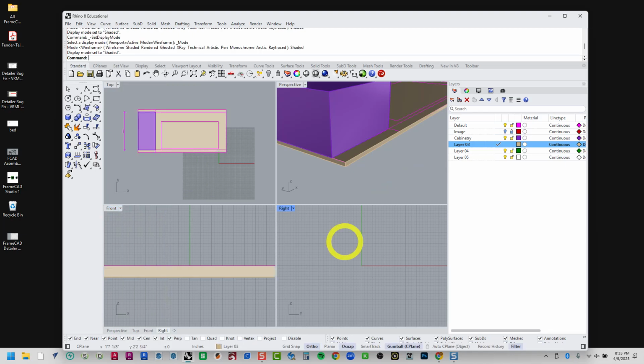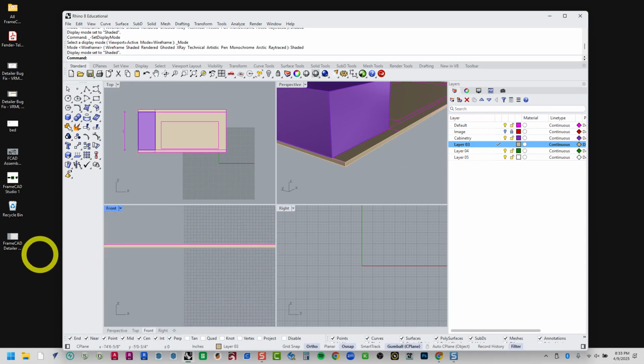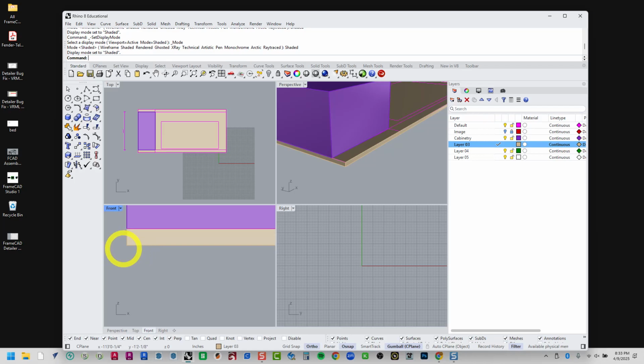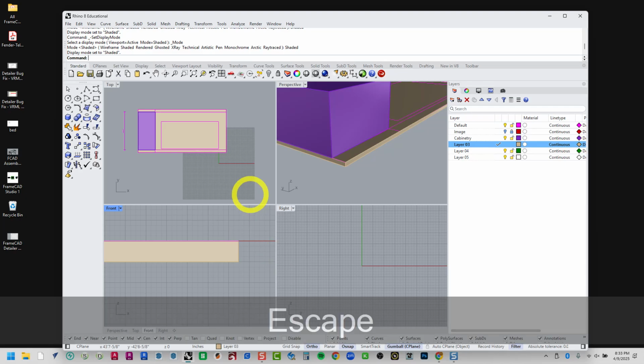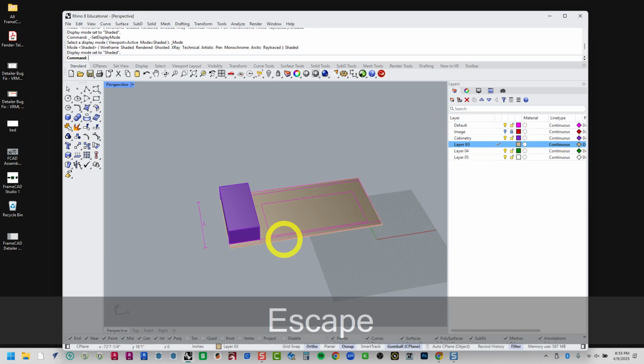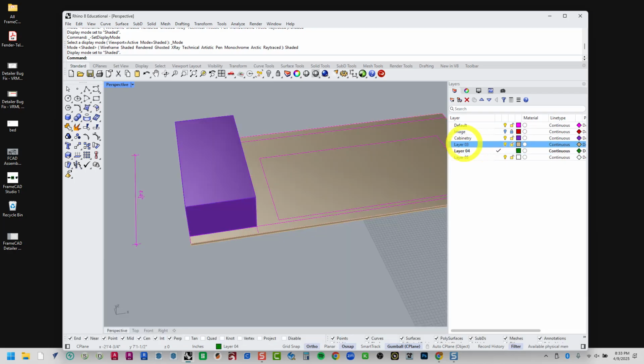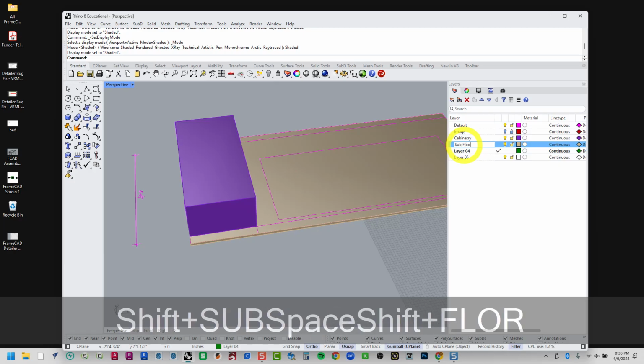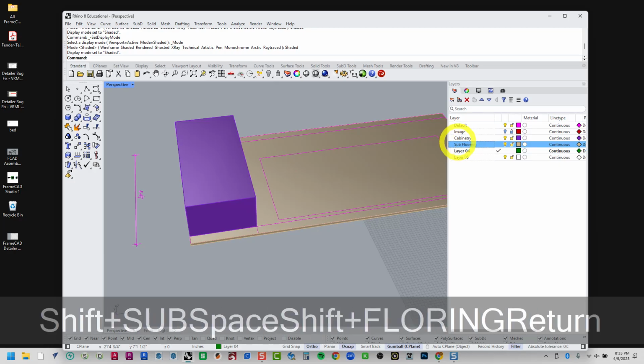All right, let's use another layer. Let's call that layer subflooring. Okay, I'm going to go to my layer 4, and we'll call this walls. And instead of green, let's pick something a little bluish grayish. Let's do another 3-point box. And I'm going to do my box from here to there, which is 3 5/8, all the way down the length of my subfloor. And now I want to determine the height of my little camper trailer, the height of my box. What is that?